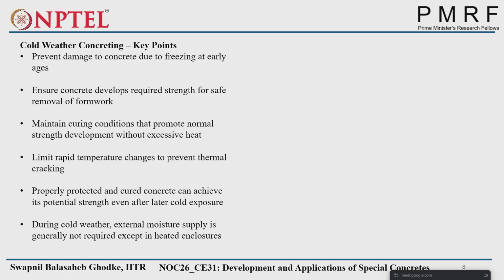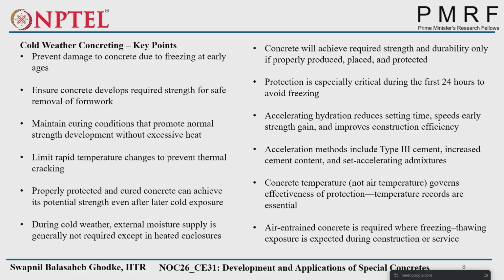And during cold weather, external moisture supply is generally not required except in heated enclosures. Heated enclosures means dry heat should not be provided. Wet steam heat we have to provide. Then concrete will achieve required strength and durability only if properly produced, placed, and protected.